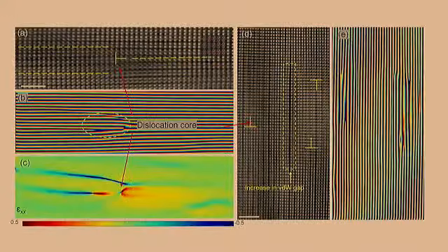But what I want to show is this: inside the tetragonal region, we get dislocations, and strain in the regions close to the dislocations. Again, I showed you the crack opening in the other case. In this case, the crack opening that happens inside the material basically leads to transformation. That is, we locally get the orthorhombic form coming up, becoming stabilized in regions close to dislocations. This is a very interesting observation, that a local strain can induce this kind of polymorphic transformation.